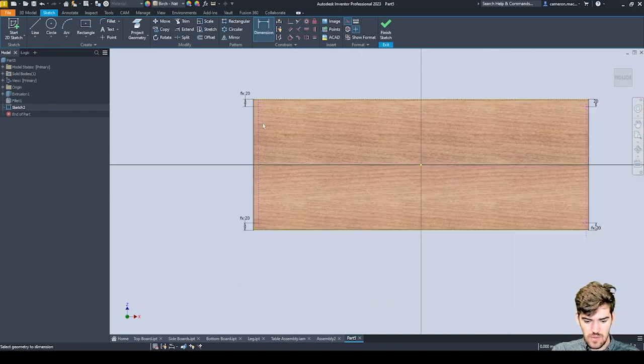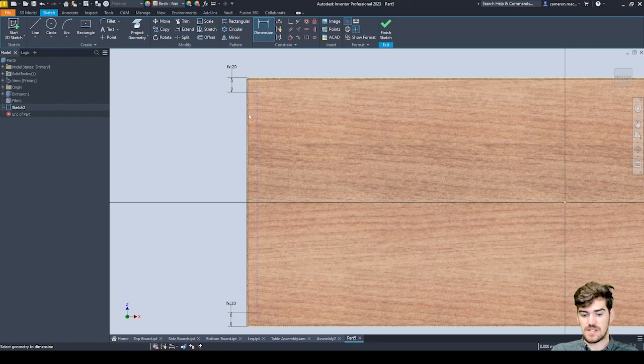And then we also want to make sure that our hole placement is correct along the side of the part, to make sure that we've got our side plates or whatever's holding up to the side is the right distance from the edge. So I'm just going to add a distance between the construction line and the edge, and I'm going to say that this is going to be equal to thickness, THK, divided by 2. We want it right in the middle of the thickness, and that thickness will be defined throughout the entire assembly.